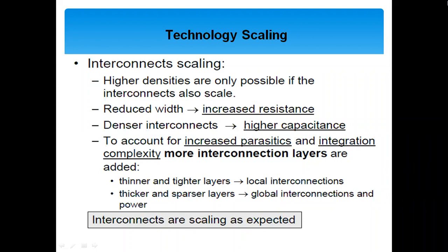So if you reduce the area of cross section, the resistance is going to increase. That means by scaling down the interconnects, it will increase the resistance, it will increase the parasitic capacitances. MOS transistor has certain extrinsic and intrinsic type capacitances, so they will also get increased.